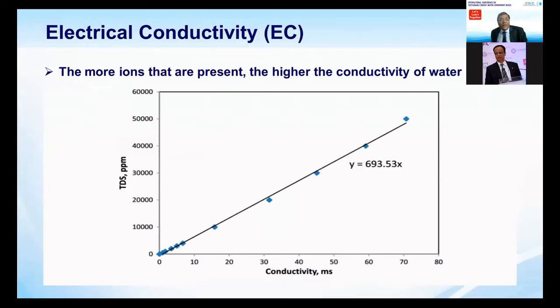And there we have the relationship of conductivity, because the measurement of TDS is by the evaporation process and it takes some time. But in water treatment technology, we can correlate the direct measure of conductivity almost to TDS. If you have 10,000 conductivity, it means you have 5,000 TDS. That is just a thumb rule for you, and it may vary by a factor of 0.5 to 0.7, depending upon the ionic composition of that sample. It is just for your reference that in water treatment we correlate conductivity and TDS.